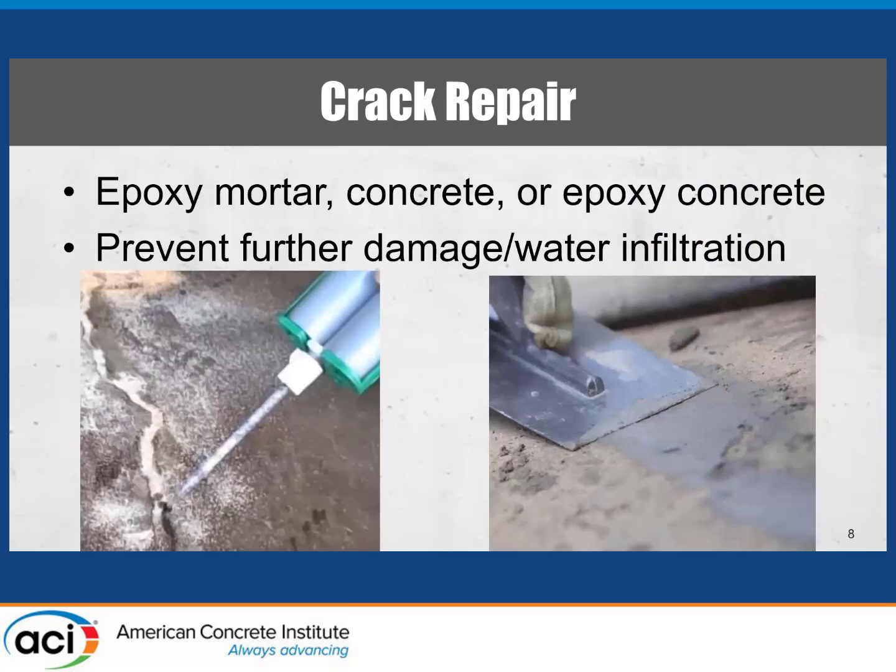Crack repair is another obvious one. We all know what happens when you get cracks in concrete. You get water inside and you damage the concrete. So crack repair, whether it's epoxy mortar, concrete repairs, or an epoxy concrete, just for some examples, is a way to help prevent further damage. That is, you're increasing the life and therefore the resistance of your structure, preventing corrosion, hopefully internally, and increasing resilience. So again, it's a way, in an existing building, to extend the life and get a more resilient structure because of that.